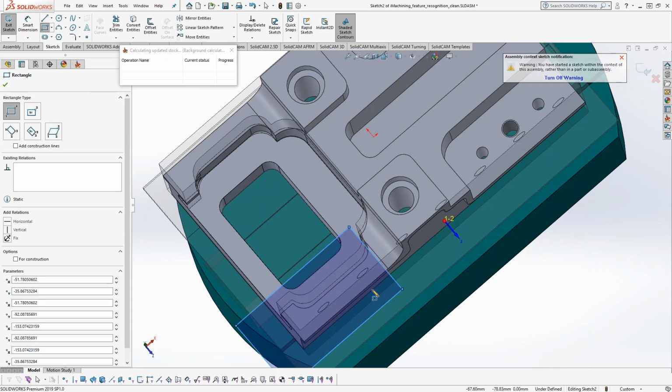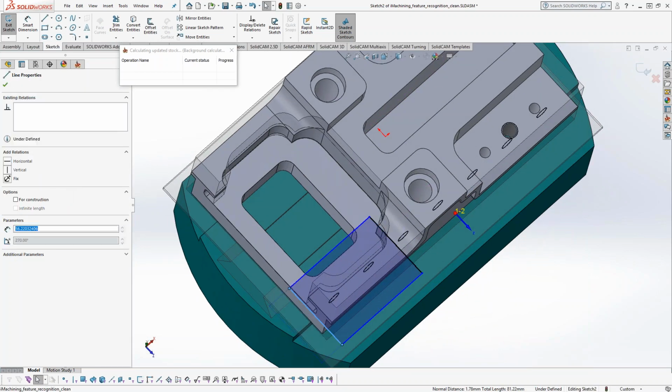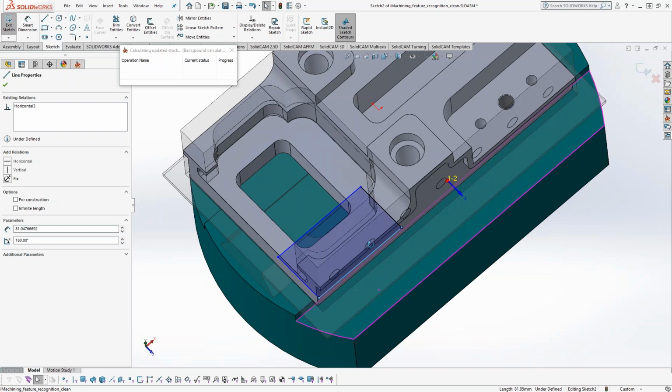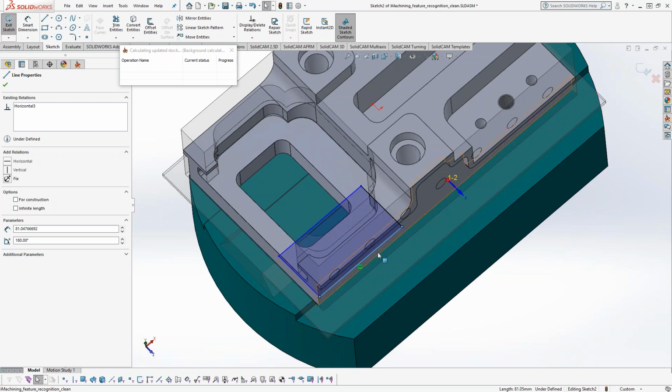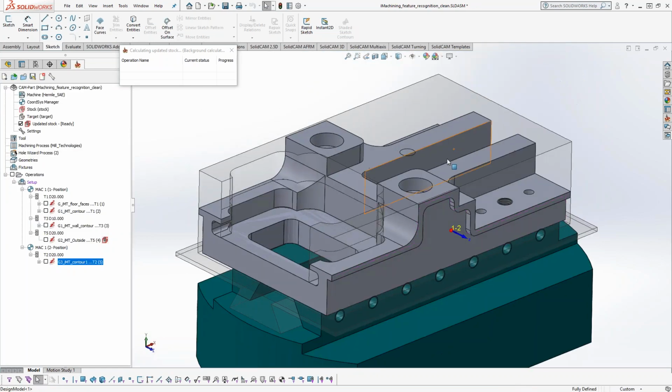I'm going to make these two things collinear, and then make a little semi-open pocket that lines up with my stock. I would use that as my chain for 2D iMachining, mark these three edges as open, and try to machine that little face away, right? But now things are much simpler.